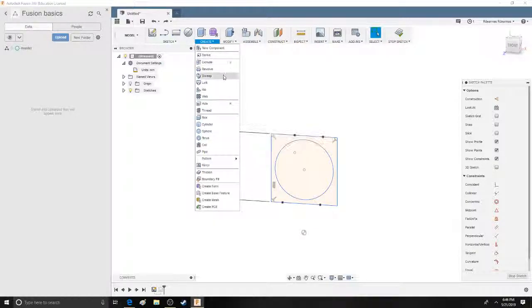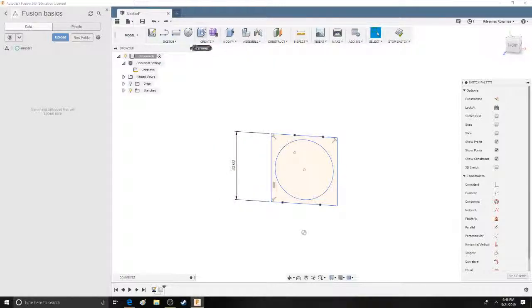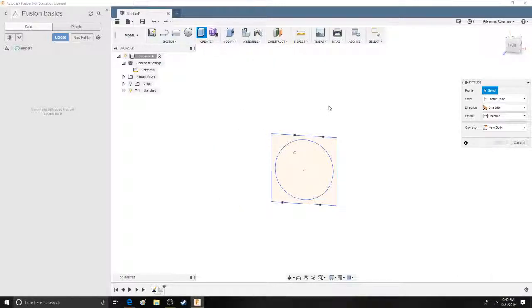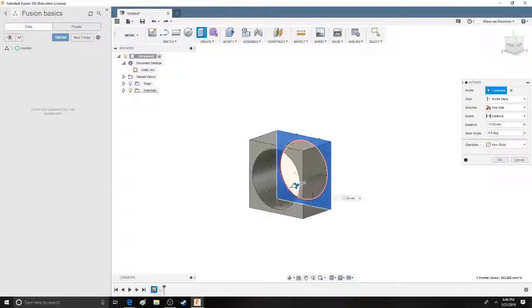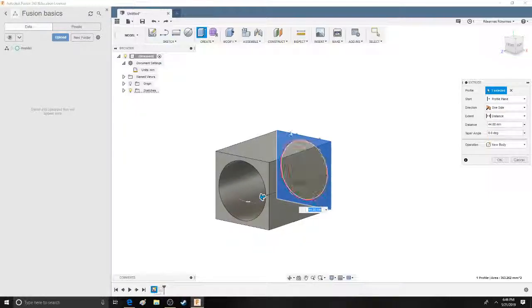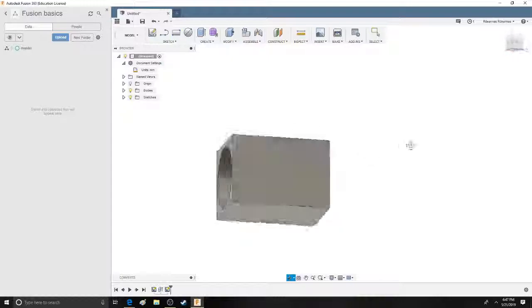That would be the extrude, revolve, sweep, loft, rib, bunch of different options. But just for this one, we're going to be doing extrude. So we go from your sketched object from being a flat surface to a 3D model. Just by clicking on one of the faces and dragging outward, you now have a 3D model.